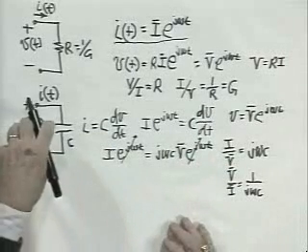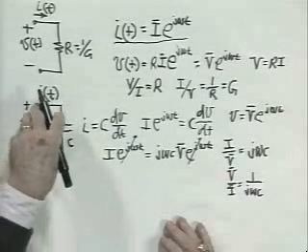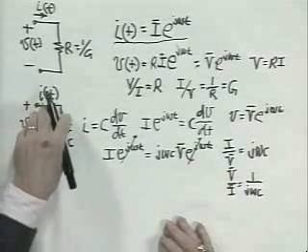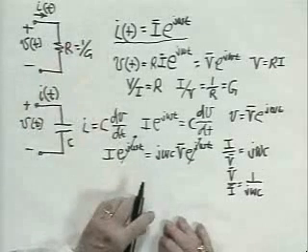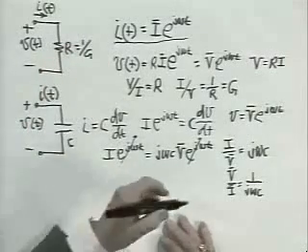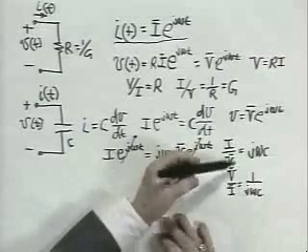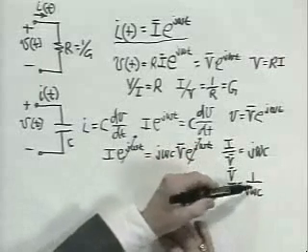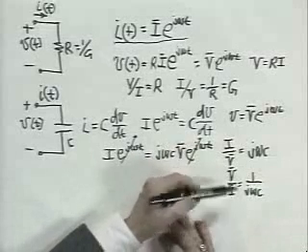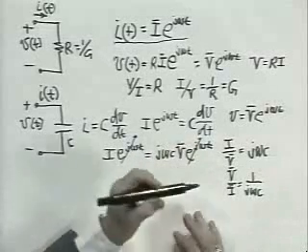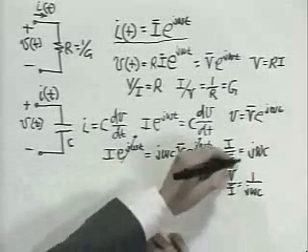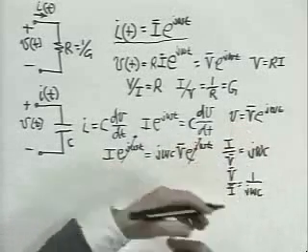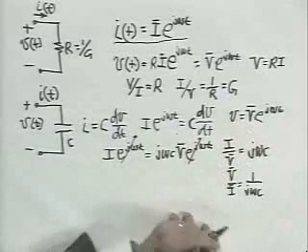So the relationship, which is equivalent in the capacitor to the multiplication by R in the resistance, is a differentiation which brings out the 1 over j omega C if I'm talking about V over I. And the relationship is still a linear one, only the coefficient now, instead of being a real number, is a complex number.